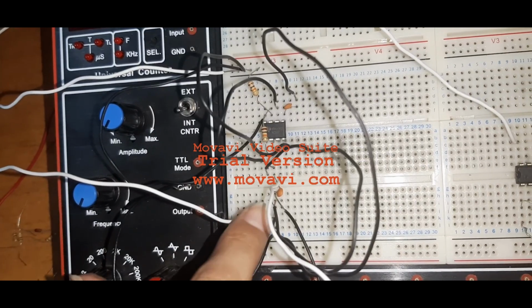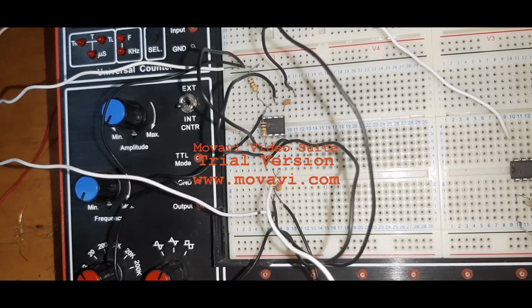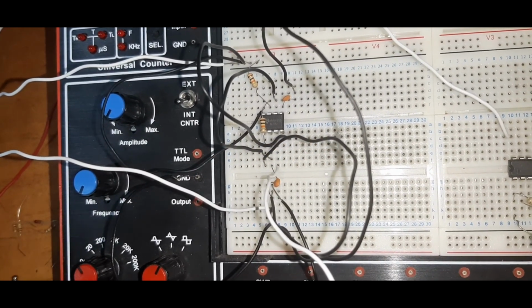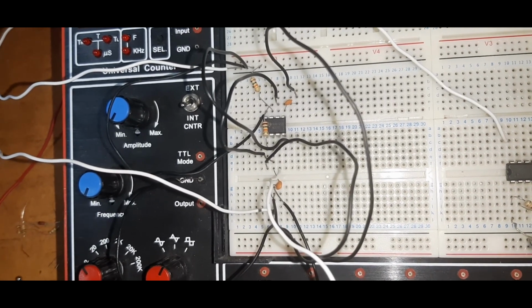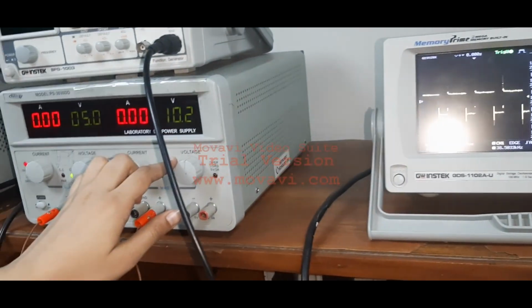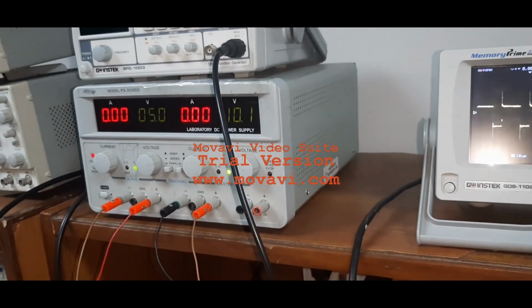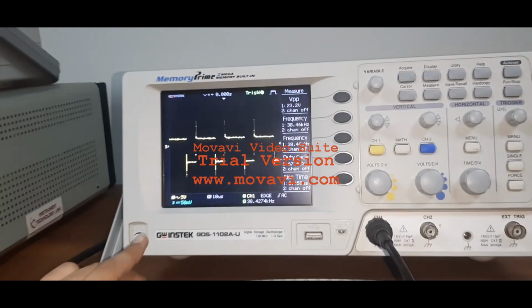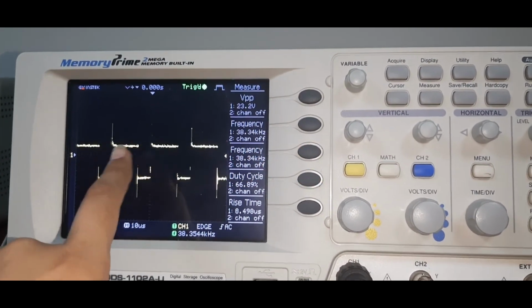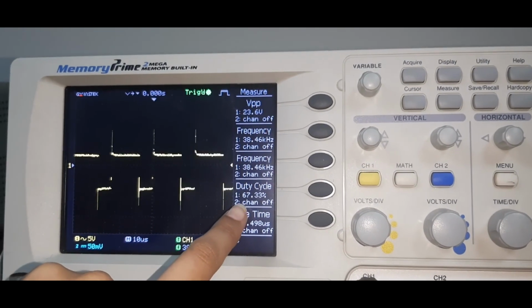You can see that I didn't apply any AC input signal to this circuit, because it is an oscillator circuit which will automatically produce oscillation using the DC power supply. I just connected this circuit with the DC power supply, that is 10 volt, and the output is displayed on the oscilloscope. You can see that here the square wave is generated with a duty cycle of 67.4%,